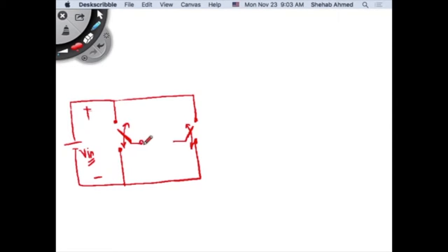And at the output, I always had, in the buck, the boost, or the buck boost, the switch current going through an inductor, right? And it's the same here. I can draw this as half the inductor here, half the inductor here. They're in series anyway, right? And then this is my load for my inverter. This load can be a resistive load, so I can put an inductor here, and then I can draw a resistor here, and maybe I put a capacitor as well. Or maybe not.